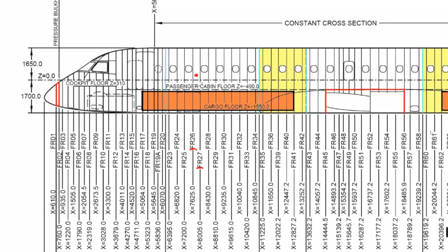In this case, if I have to do some evaluation, I will use the passenger windows. When I count the windows, the second window on the left side, I will check this schematic and I will see that my damage is between passenger windows 2 and 3. I will cross-check and see that between frame 26 and 27, this is my damage, exactly between the second and the third window on the left side.